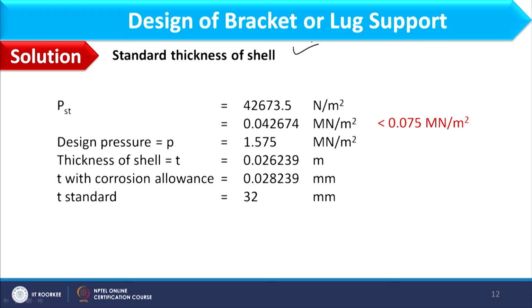Okay. Now, if you consider this problem, it has operating pressure as 1.5 mega Newton per meter square and liquid is available up to 5 meter height. It means it has static load of liquid also. So, when this type of condition is there, when I am having operating pressure as well as static head of the liquid, I have to compute the design pressure in a slightly different way. For that, first of all I have to find static load of the liquid, that is rho gH of the liquid, and then I have to compare that with a condition.